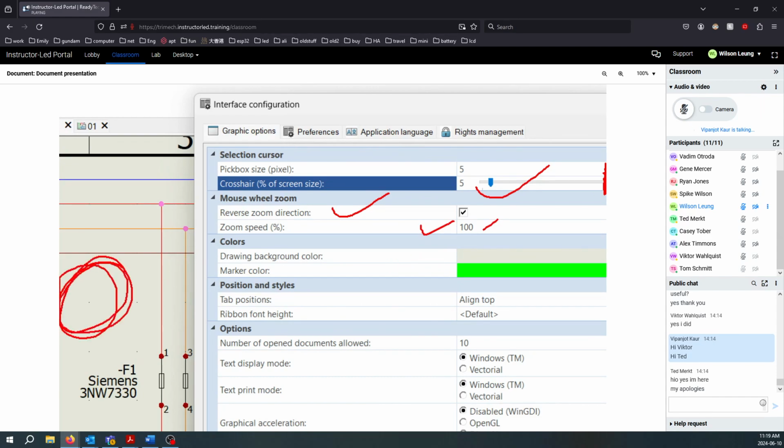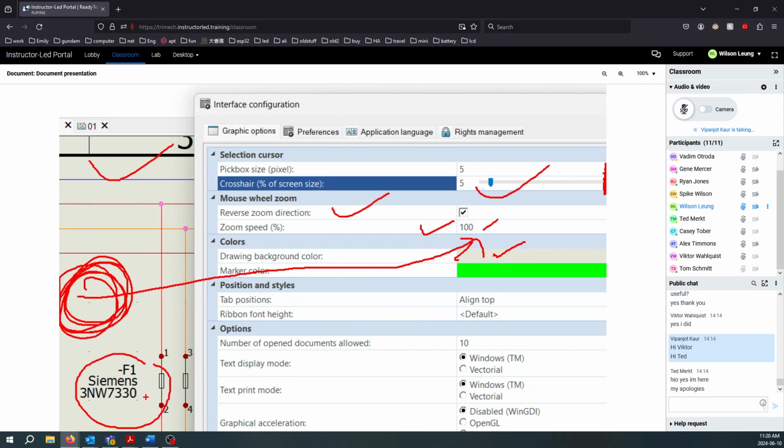Background drawing color. So this creamish color that I have is what you see here. If you're working with AutoCAD, often you're used to the black graphics area, and you can change this to black. You should not have any problem with the text here, since, as I will show you, in your text properties the text color is black/white. If you've got a dark background, it's going to automatically pick a whitish color. If you've got a white background, it will pick a blackish color for the text.